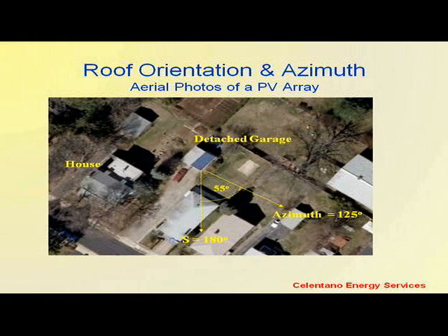And you can see that here's due south. His garage roof is tilted 55 degrees away from due south, 55 degrees away. We call that an azimuth of 125 degrees, which is 180 minus 55. Even so, he's really only losing a rather negligible amount of electricity. So you can be 45, 55 degrees tilted away from due south, and you're still going to be getting good production.